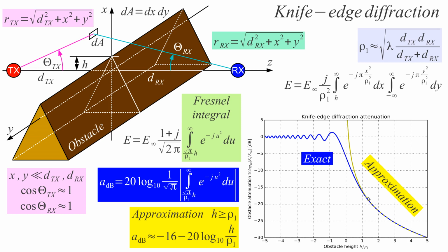So, in order to have almost free space communications, this h should be minus rho 1. Minus rho 1, well, here it's almost there. We have also an overshoot here, but this overshoot is small for practical reasons. It's slightly more than a dB here, so this is really small. The problem is this thing here. The problem is when the diffraction loss increases, the signal decreases down here.